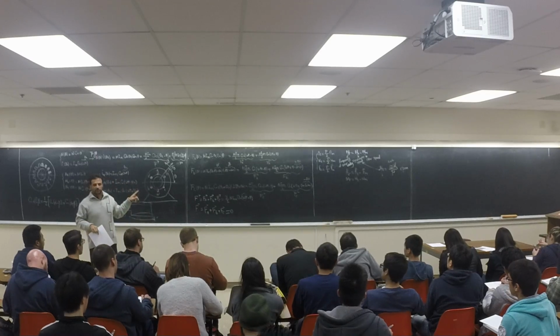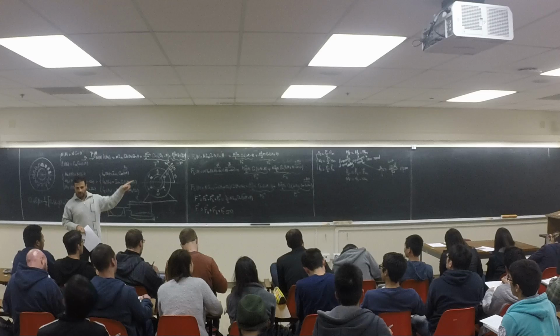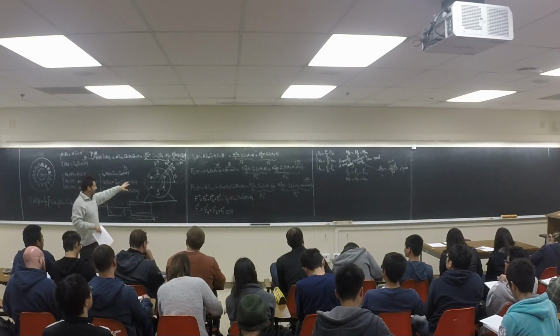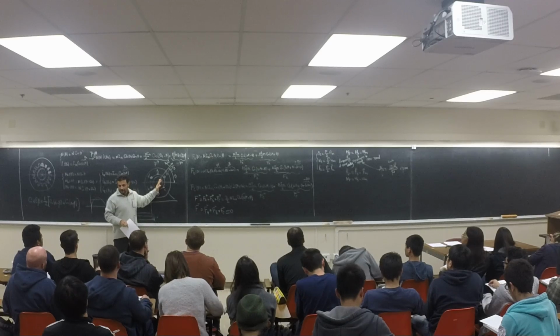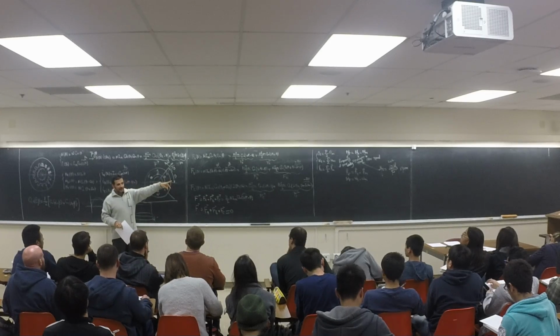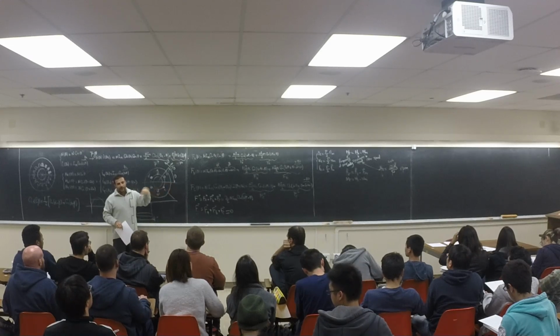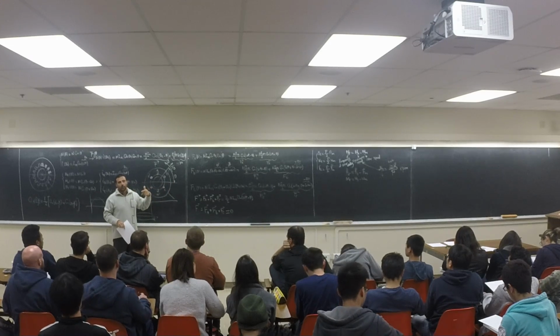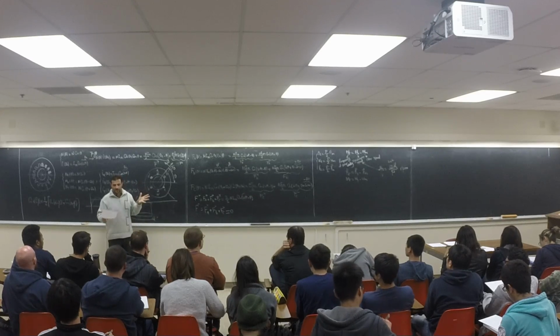And we have a synchronous machine. When we get there, I'll explain what the synchronous machine is. It's coming exactly from here. If you look at here, I said the rotor is rotating with Nm, right? It's not Ns. They call it induction machine or asynchronous machine. Asynchronous means they are not synchronous, right?